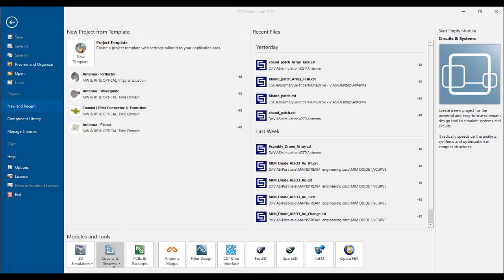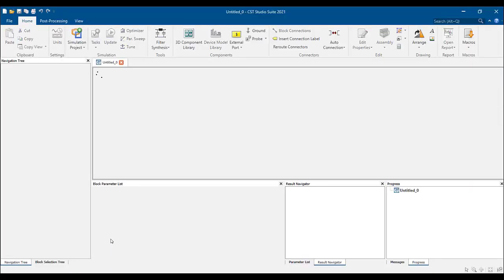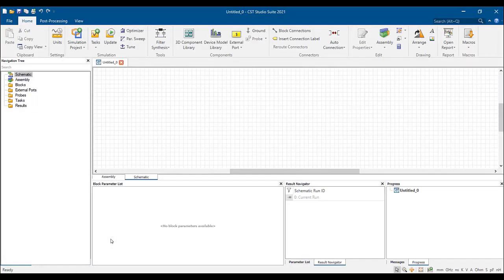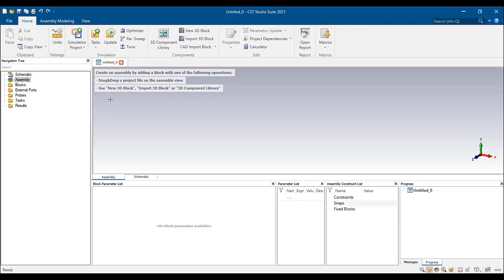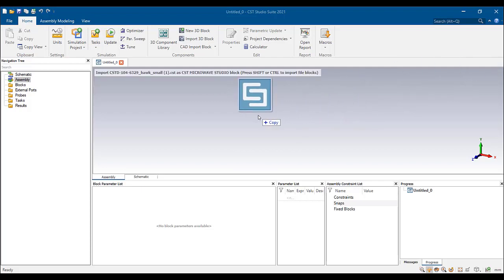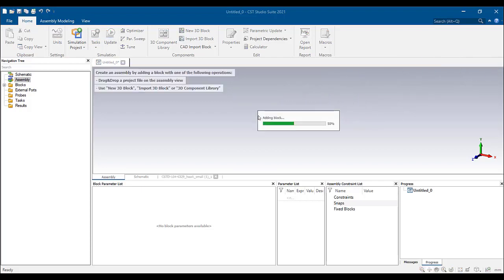Another feature in CST is antenna placement. CST offers electromagnetic solvers for all electrical sizes. With increasing electrical size, high frequency solvers are the recommended approach to efficiently handle large electrical size. That's why, in this case, we're going to use assembly mode. We are going to analyze the performance of the full array on a drone.